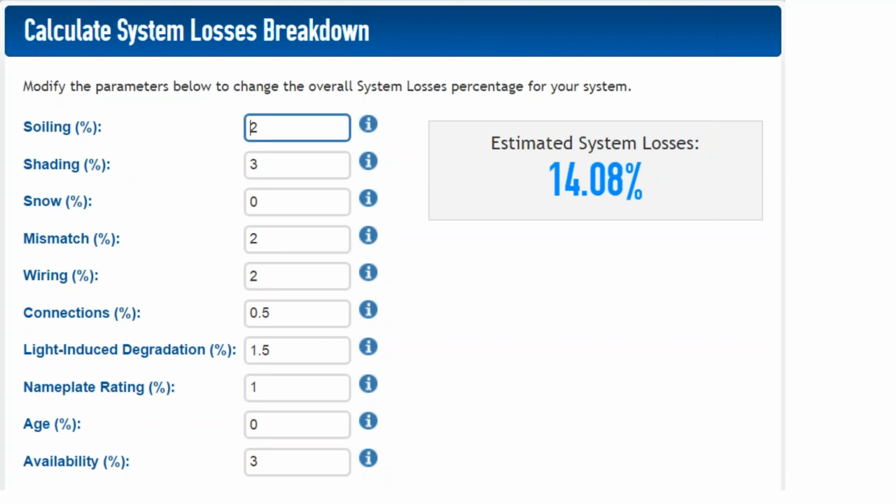It also is not including things like, if PVwatts is showing at 6 a.m. that your solar array is producing, say it's a 1,000 watt array, at 6 a.m. it might be producing 6 watts of power, 0.5% of power. Well, in reality, that's not going to be enough power to turn on and start up the system.